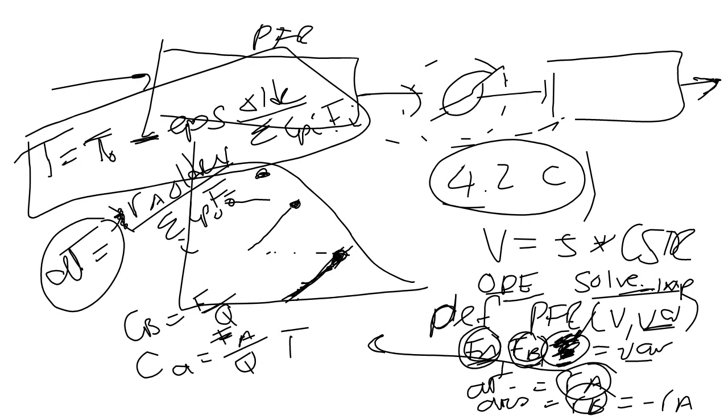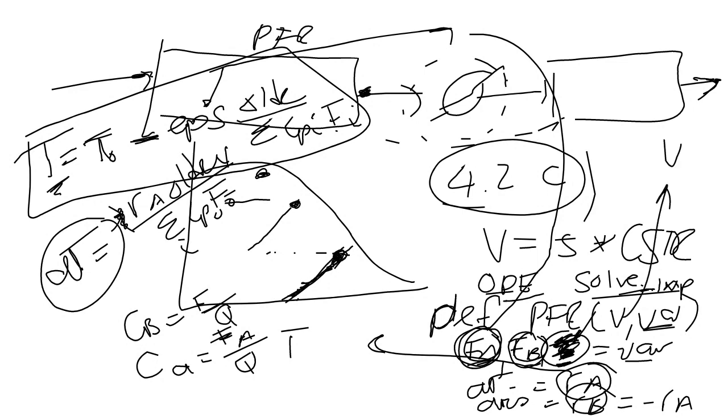Okay, so this is the algebraic equation that you're going to use, and the epsilon you will then have to write in terms of your FA that you have calculated there. But now if you are at the outlet, so this is there, and now you have an outlet for that PFR. First thing I want you to do is to solve for a very large volume. So no events, just see what happens to the profile.